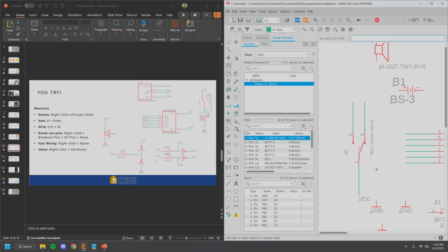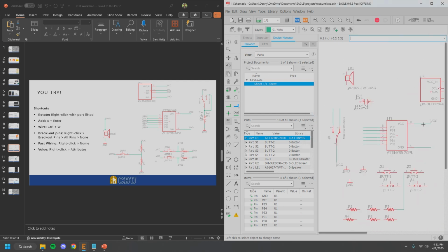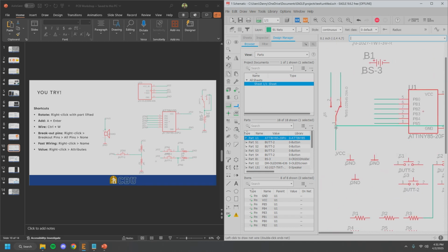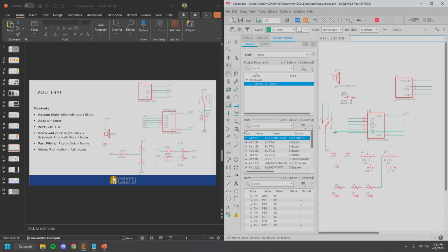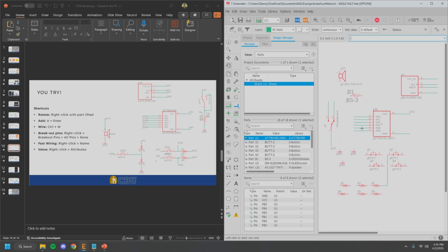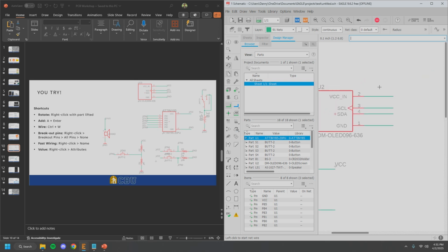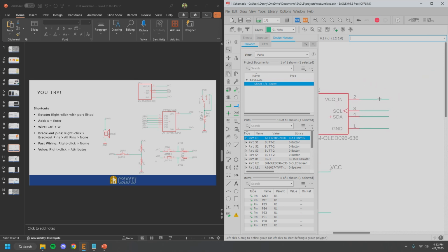And you say yes. So what this is doing is essentially the same as saying if I were to click net and wire this all the way over here, it's doing the same thing. These are now connected on the same plane. And as you can see here, that's what is done for pretty much every single one of these components.